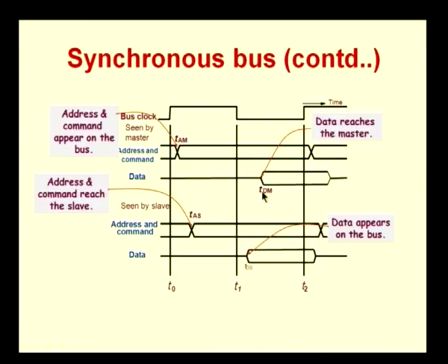This time over here, that is between TDM and T2, should be at least, this time TDM to T2 has to be greater than the setup time that is required for this master to read in the data. And similarly, you can see that the data is held onto the bus for some more time, which is definitely greater than the hold time that is required for the master to take in the data. So, you can see that the address does not change before that, and the data does not change at T2. It is valid some time before T2, and valid for some time after T2.